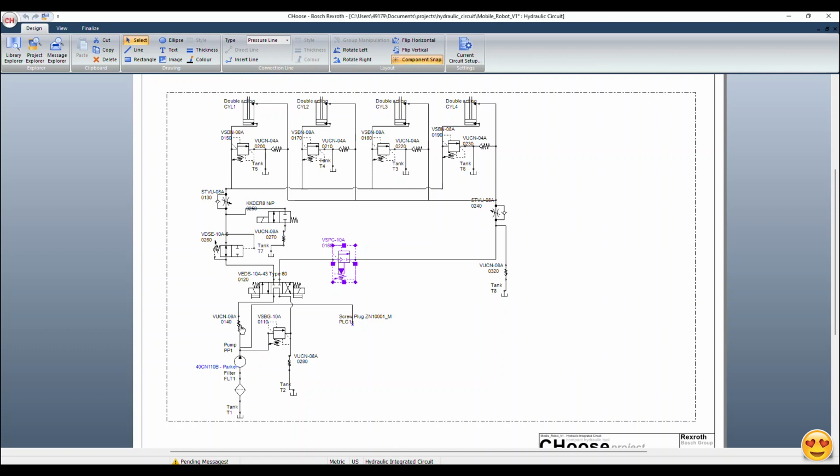This one is a kind of valve, so-called, I think, a check valve, that ensures there is no flow back to the pump. It means there is only one way, and the flow of the pump always goes this way, because if there is a possibility of flow back, it could damage the pump. That's the reason they put something like that. It reminds me of a rectifier, something that makes the flow go in one way.